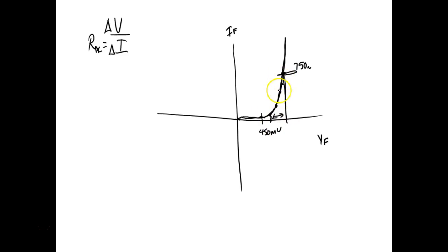And you're not worried about the slope, even though it's a slope, because it's fairly linear once we get past 0.7 of a volt. So they'll probably do it up here where it's actually fully turned on, not where it's trying to turn on, where it's fully turned on. So we want it to be above the knee, or whichever way you want to call it.